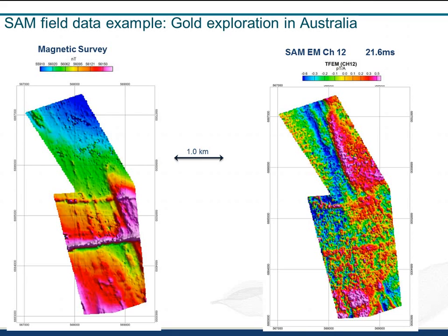So this data set provided high resolution reconnaissance style surveying for this particular area. They're in there to map a large area rapidly, and you're able to derive several parameters of the data set: mag, resistivity, EM. And if you set it up differently, you could have collected IP information as well. And the survey provides good depth penetration.